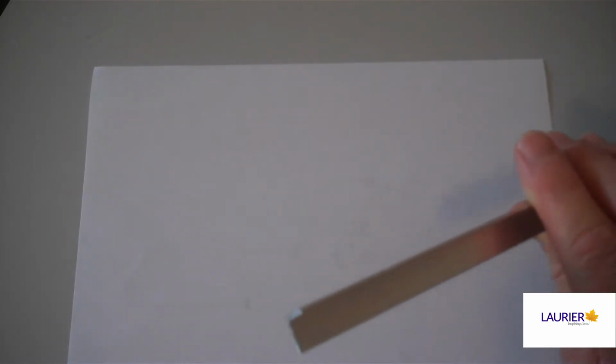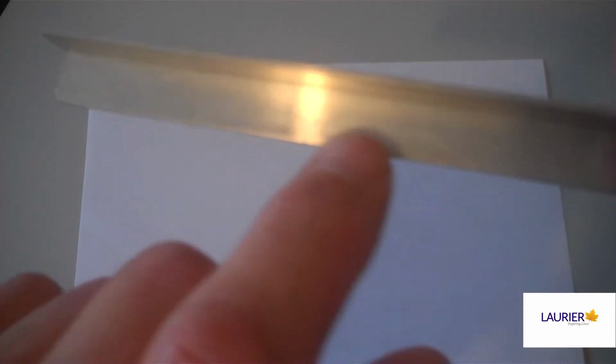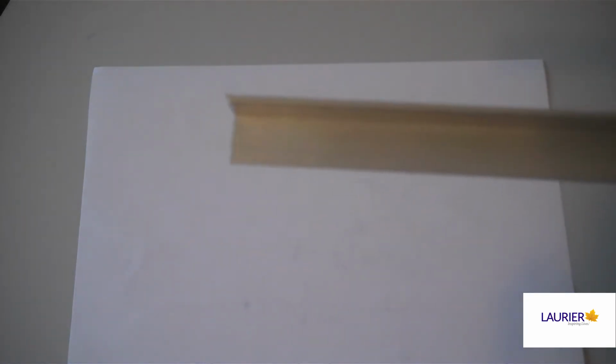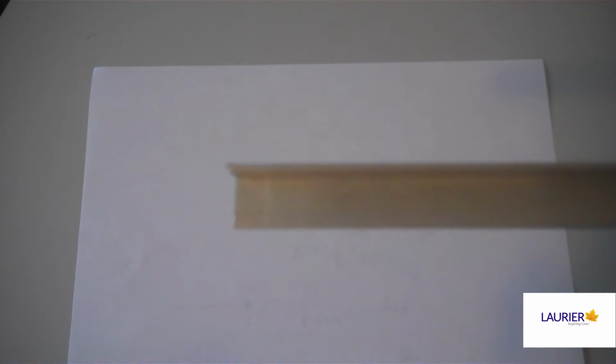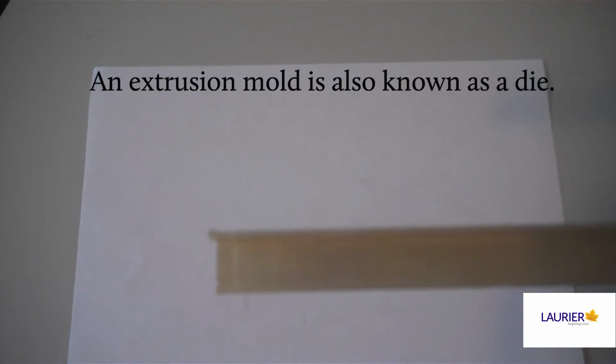And we're back. Industrially, a lot of important components are made using extrusion. Take this aluminum angle stock, for example. If you look really closely, you can see some scratches going along this lengthwise. Those little surface scratches are actually from this material traveling through a mold that has an L-shaped hole in it as a semi-solid paste before cooling into a solid in this angle shape, all while traveling normal to the plane of the die opening. Given an unlimited supply of aluminum, a piece could be made an unlimited length. It's the same idea as toothpaste, but it doesn't help oral hygiene one bit.